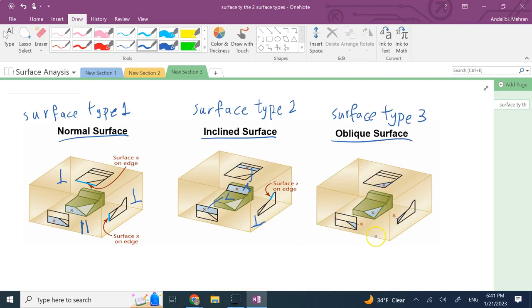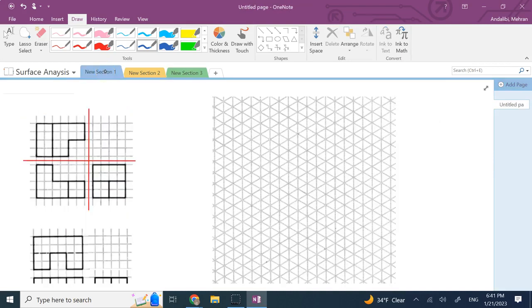Now, knowing all of that information, let's go ahead and do the surface analysis method. So what we do here is, any surface that we see in these views, we give it a name, okay? So in the front view, we start, if we call this A, and then I call this guy B. Now my first question is: in any of these other views, the top and right, do I see A and B? And if I see them, is that another surface or is that an edge?